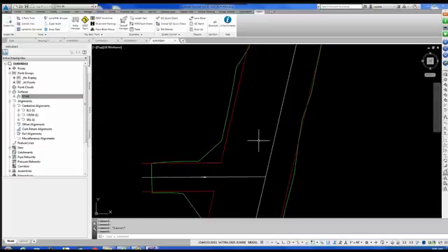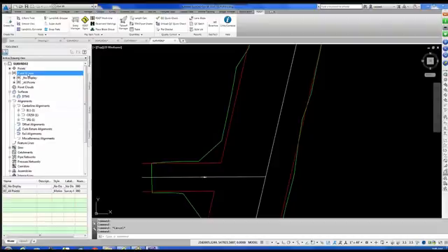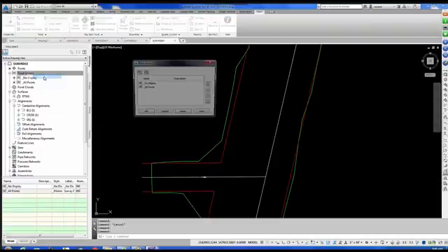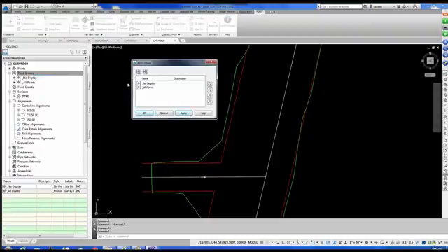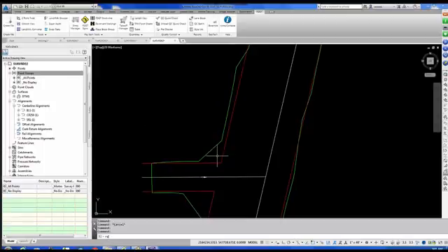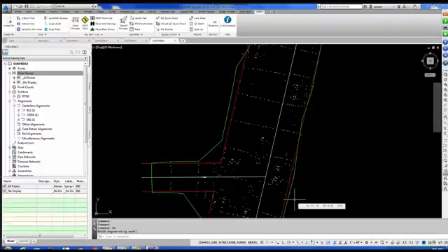Okay. Now, do you see how there are no points displayed anymore? Remember how the point group no display had to be updated? So what I'm going to do here is I'm going to pick on point groups, the category point groups. I'm going to right click, and I'm going to go to properties. And the way the software works is it says, okay, reading from the bottom of the list up, what do you want me to do? Display all the points. Then it hits that point group called no display, and it says, okay, that point group is set up not to display any point objects and not display any labels. So if I pick on all points, on the right-hand side here, I've got 4 arrows. Move it to the top all the way, move it up 1 bump at a time, move it down a bump, or move it all the way to the bottom of the list. I'm going to put it to the top, hit apply, hit OK, and I may have to regen my screen, and now my points have come back.